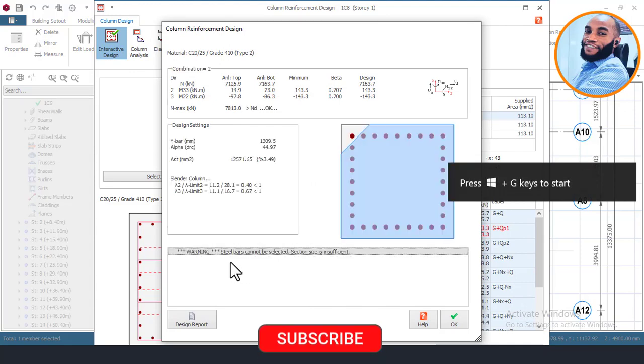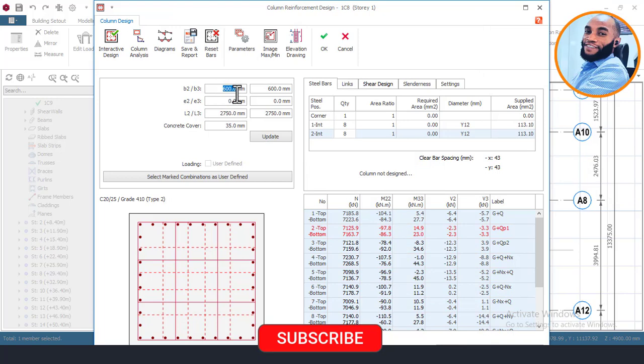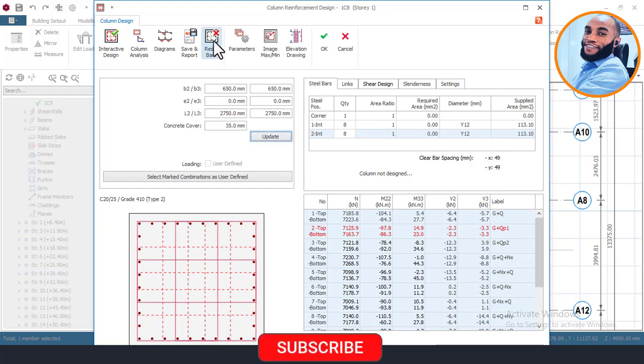And I'll come again right now, click on this place here, design first to see why it's failing. And this is the failure, that the size will be increased. I'll come here and say okay, and then come here and increase it. But most times, it might not be the size that you're going to increase. You can just go and increase the bar size and all that. So make sure you check first why it is failing, and then come here and say update, and then click on reset bars here.